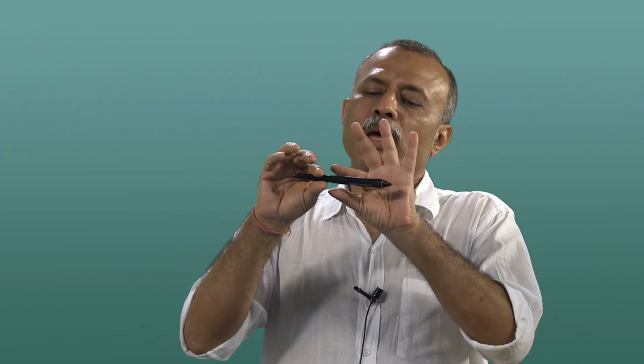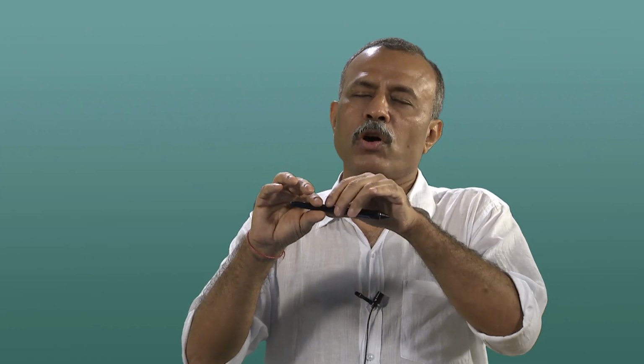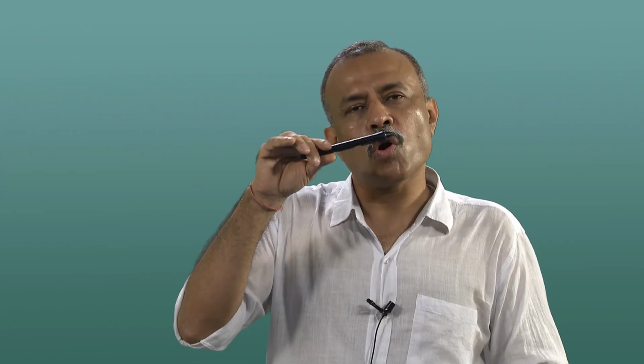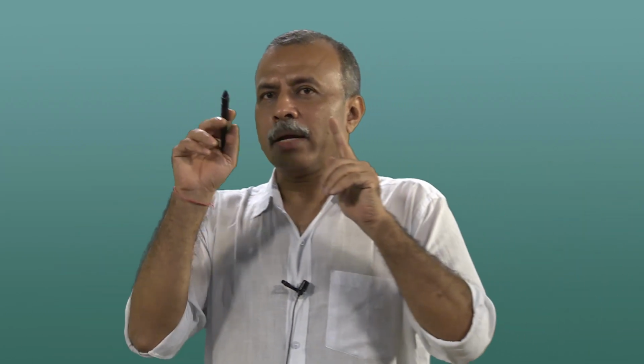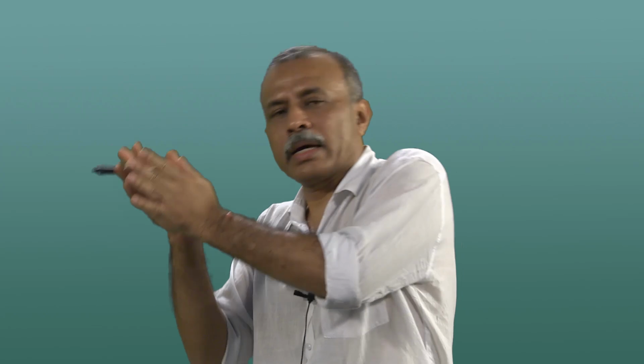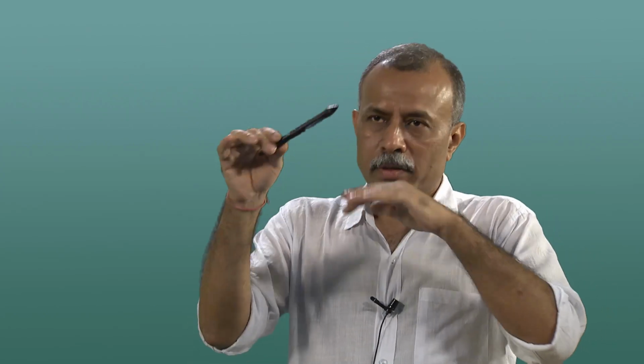So, if you use a sensor which is already imbibed with water or has absorbed a lot of water, then you have to alter the equation, because your baseline frequency has completely changed, and your basic theory is not going to work here, that delta m is linearly related to delta f, where delta m is your change in mass and delta f is your change in frequency, because in this situation your frequency is working in a very different way. There is a dissipation because it is absorbing.